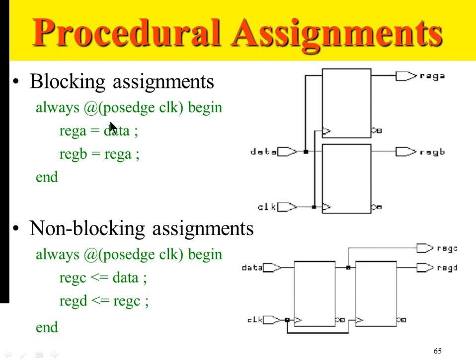Did you get the difference between blocking and non-blocking? Yes. So now I'm telling you that we will be using non-blocking for design purposes, not the blocking one. We will be using non-blocking assignments everywhere.